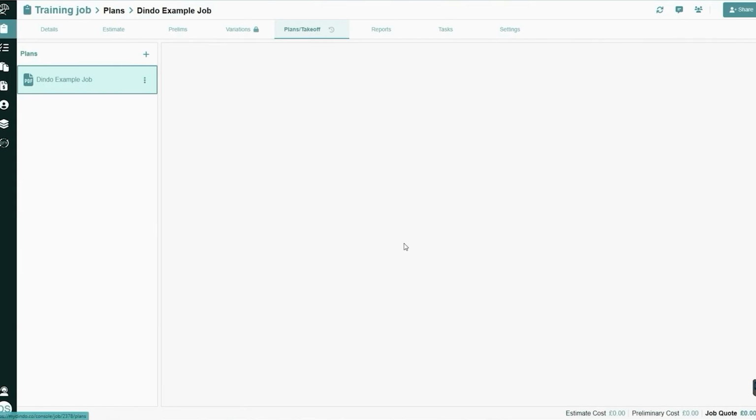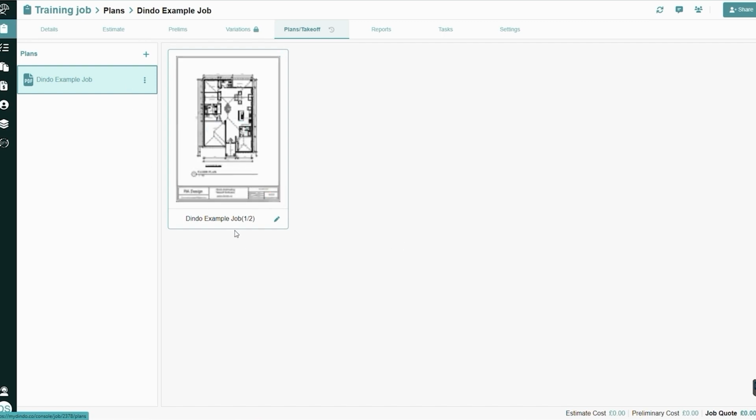And up goes the file. So one of the things you can do here, which I think is really handy, is you have all these options about renaming the plan, but also the plan group. The plan group here is on the left, and that is given the name of the first plan that comes in, but I could rename that to be structural or superstructure. And then I could add more plans in this group by going upload PDF into the superstructure.